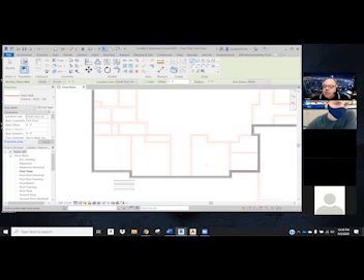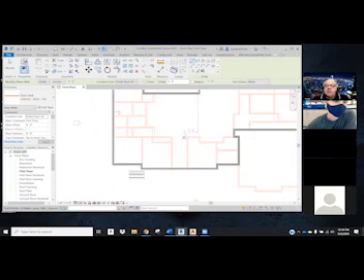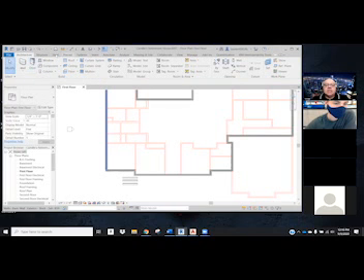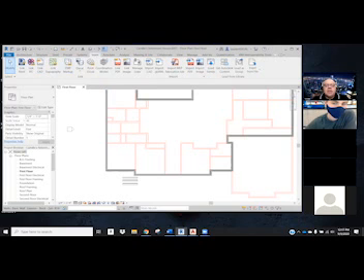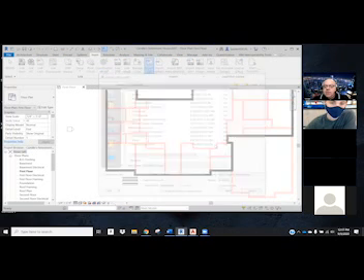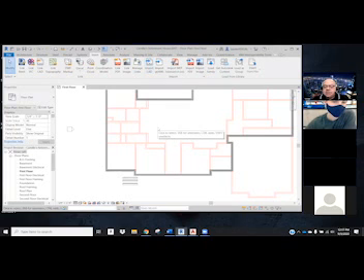Okay, Victor, to put your AutoCAD into Revit, here are the steps for that while they're doing their walls. You come across the top to the word Insert. Then you select Import CAD right here. That's going to bring up a dialog box where you can search and find your plan. You hit Open and then you place it into the drawing. That's all you have to do. Okay, that's for Victor.